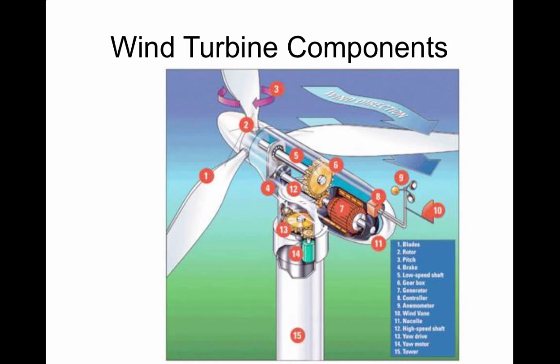And here, you've got large wind turbines that spin very slowly, so it's difficult to directly connect them to a generator, which wants to spin at a higher speed. So you've got gears here, and these gears don't generate more energy. They just translate the slower rotation of these big massive blades and this big shaft of the wind turbine to a higher rotational speed of the generator. Same energy all the way through. It's just a higher rotational speed here and a lower rotational speed there.